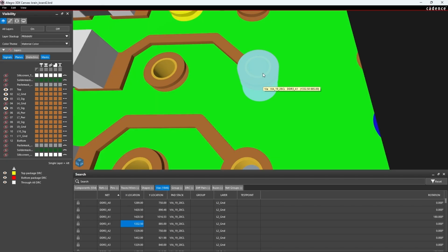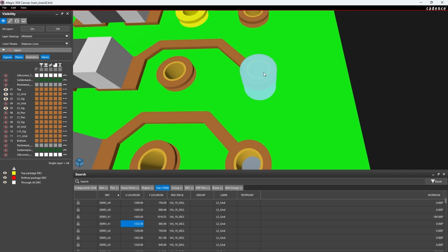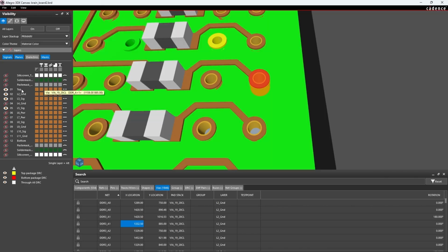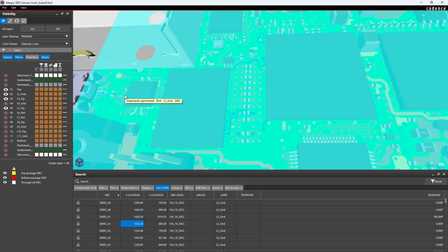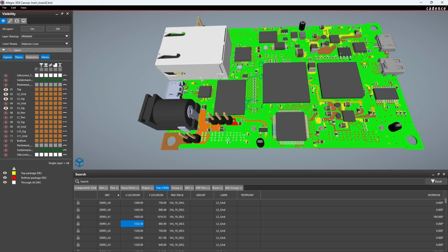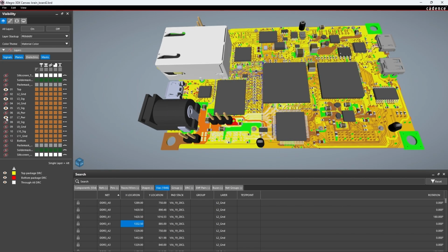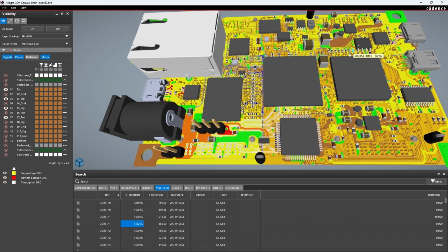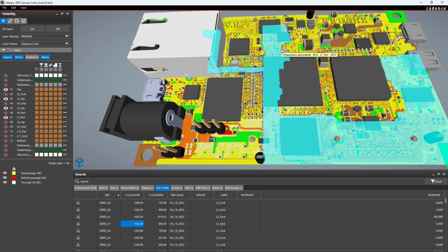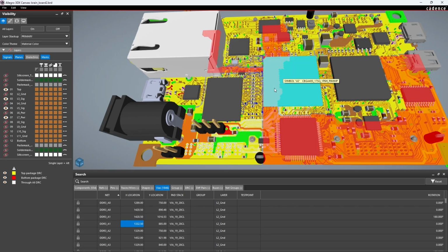Okay. So another solution for the current density problem is having wider plane connections. You see how we have ground all over this entire PCB? Well, if you have power nets, you're going to want to make those as wide as possible. So we see our shapes here, our power net shapes, that when I move my mouse cursor over, they're highlighted and they provide enough distribution for those electrons to flow. That's another way. So wider plane connections.